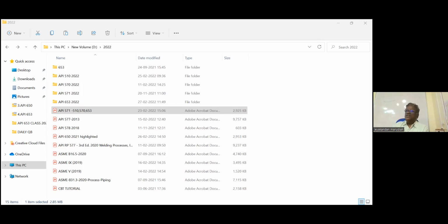Next one is, what are the other alloying elements? Steel generally will have chromium. What is the purpose of adding chromium? For corrosion resistance and for improving the toughness. So chromium is for corrosion resistance and strength. Nickel is to improve the toughness. Molybdenum is to improve the creep resistance at high temperatures. So these are called alloying elements.